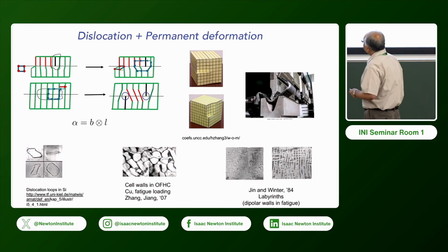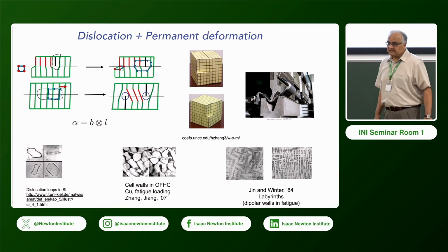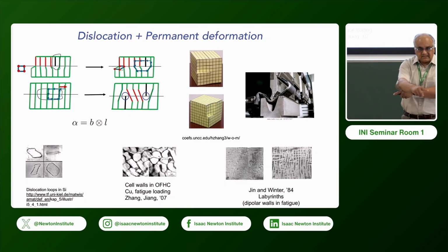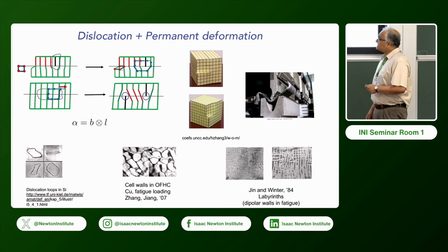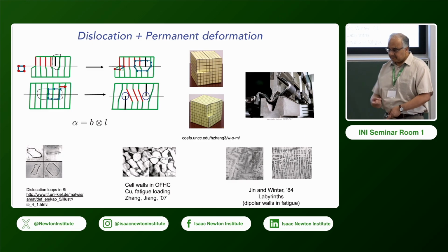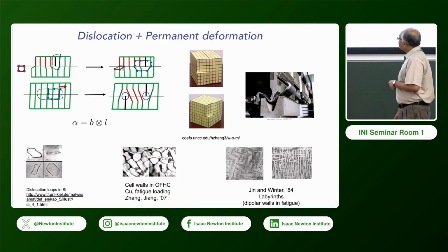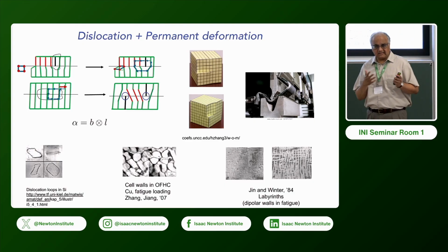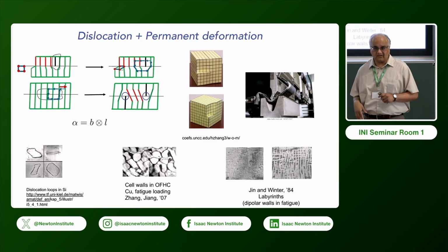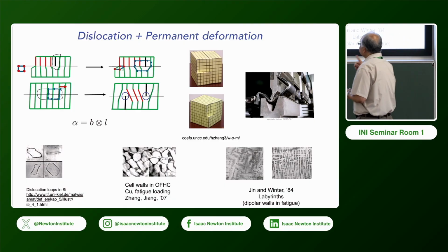And typically what we're going to characterize it by is a tensor, which is the Burgers vector tensor product with the line direction locally. So you follow this. So that's all good. I motivated this in terms of the edge dislocation, but these things are curves. They can be curves in the body. Burgers came up, same Burgers of the Burgers equation in fluid mechanics. His brother was a crystallographer, so he learned some crystallography from his brother, and he came up with the screw dislocation.